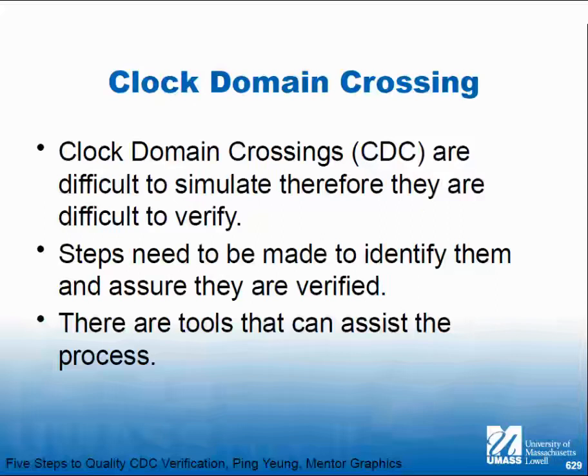Now, the hardware methods that I've talked about aren't even really perfect for verifying clock domain crossings, but at least they're more real. Here's the problem. What you're trying to filter out in a clock domain crossing is the fact that you have two signals generated by different clocks that have an undefined but continuous relationship to each other.